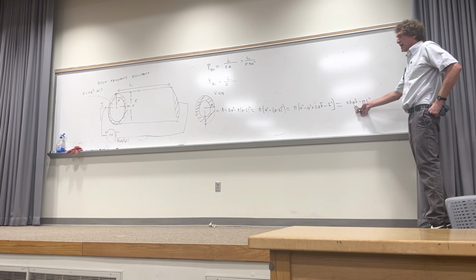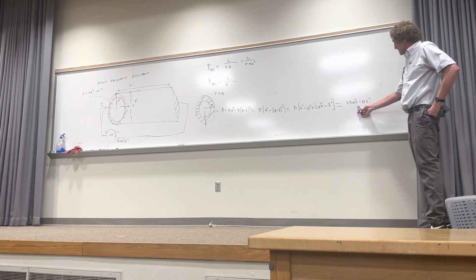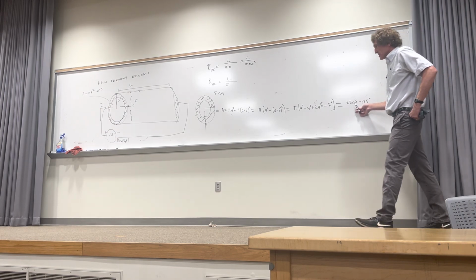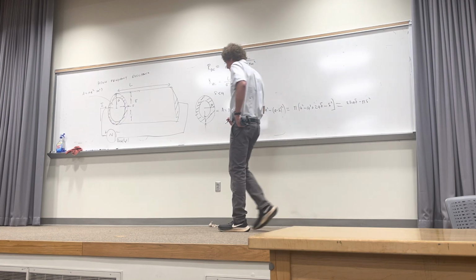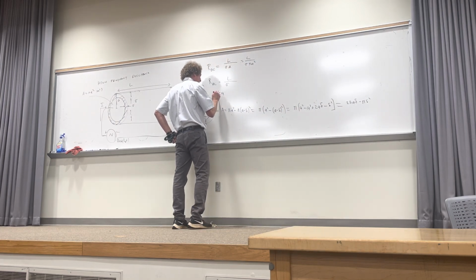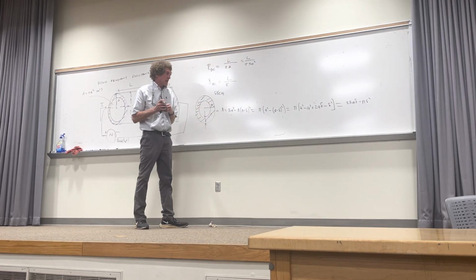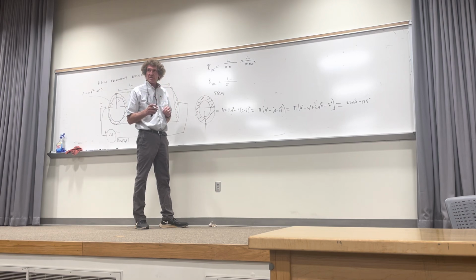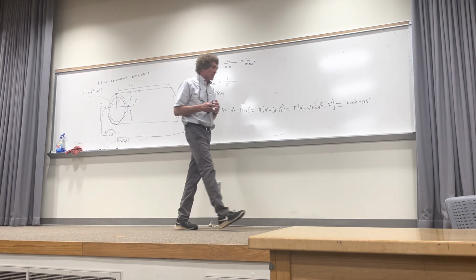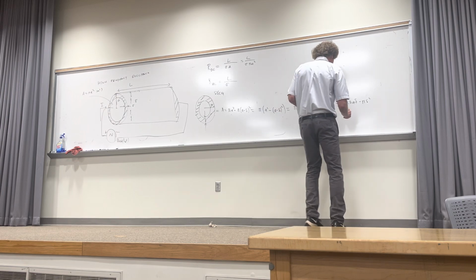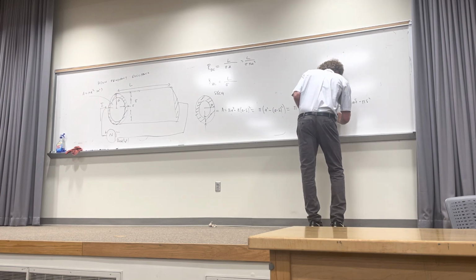Usually, for this to work, A has to be greater than the skin depth, delta. It's usually much, much greater. As a matter of fact, in almost all cases, you find that A is much, much greater than the skin depth when we're talking about skin depth variations of resistance. And that means, therefore, this area becomes approximately just 2 pi A skin depth.